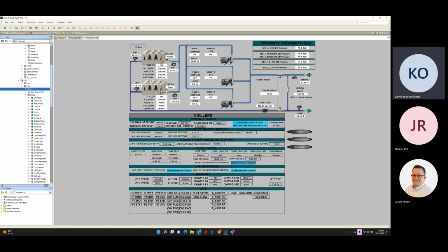We did a low select off of GPM or differential pressure, whichever one goes below set point, that's what controls to ramp up pumps. So the pumps are always maintaining at least, in this case, let's say 125 or 150 GPM and at least 20 PSI in our lowest zone. And if any one of them slides, the pumps ramp up.